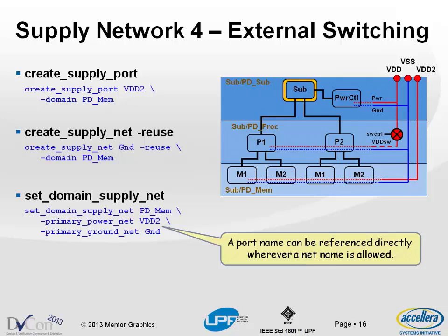And in UPF, the semantics are such that you can just sort of implicitly refer to the port as if you had created a net with the same name and you're using it directly. So kind of a nit, but something that gets in the way sometimes.